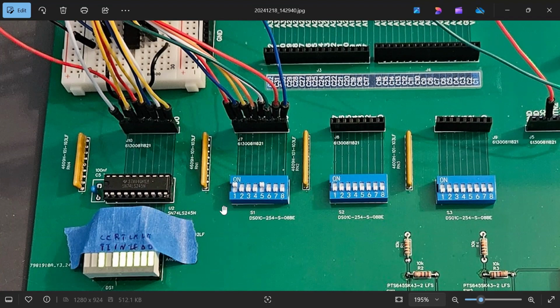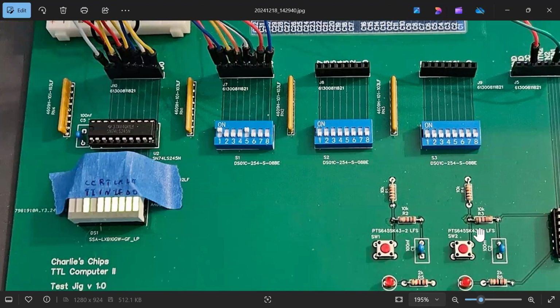But then when I put this back to high, it was relatching the instruction register input, and the tick counter reset signals were being latched in again, and I just couldn't understand what was going on there. It just completely shouldn't have been happening, because the clock signal for the latches is the P clock, which is here. It has nothing to do with the not clear signal. So I didn't know what was going on.